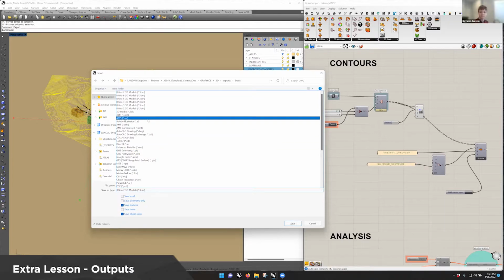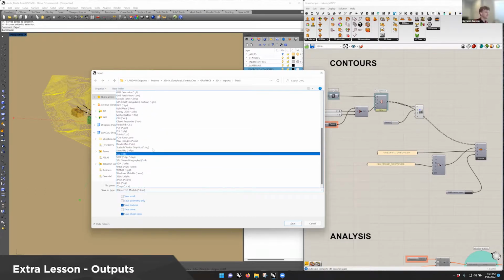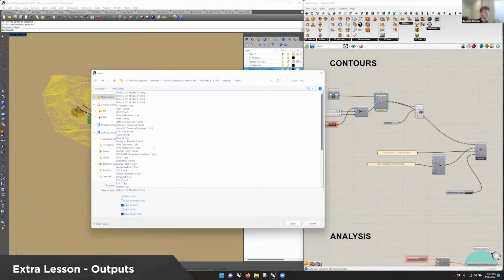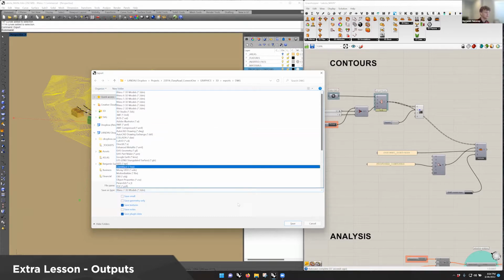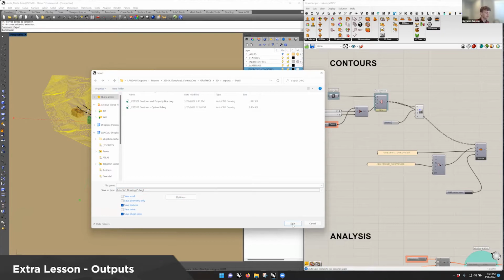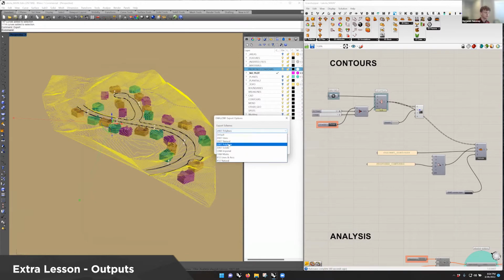There's a few big softwares that you can't export to, but there are definitely a range of different exports that will work across every software. So we haven't ever run into a major snag for exporting, but it has the DWG drawing for AutoCAD, and you could export these to an AutoCAD file and bring them in. Save, and then you can choose 2007 natural polylines, and then all those will come into AutoCAD as polylines that could be easily changed and manipulated as polylines in AutoCAD software.